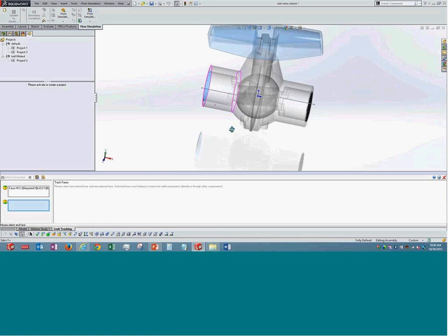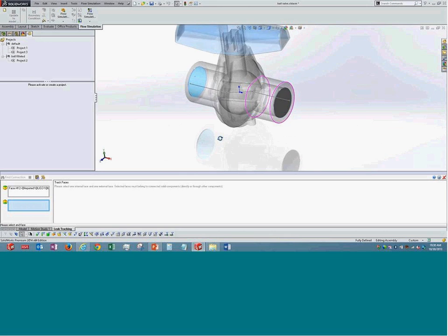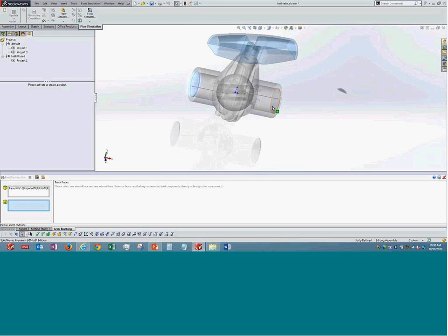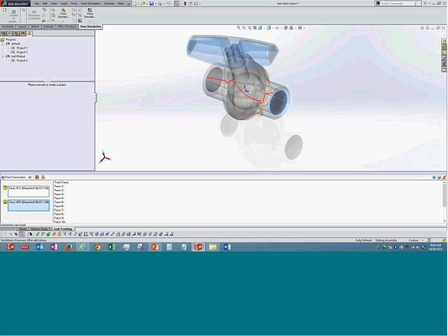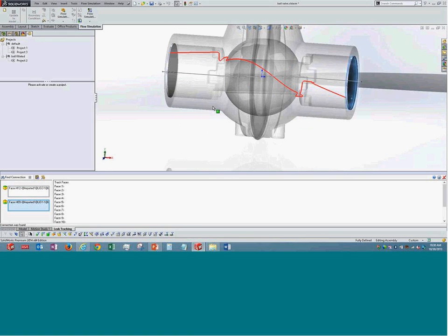I have not even created a flow simulation setup. It is just showing you how it is going to flow from these faces that are selected. There can be a case when I don't have a lid over here, or there are some holes, etc. throughout the setup, and with this option you can understand how it is going to leak out of the setup. Find out those locations and fill them with lids.